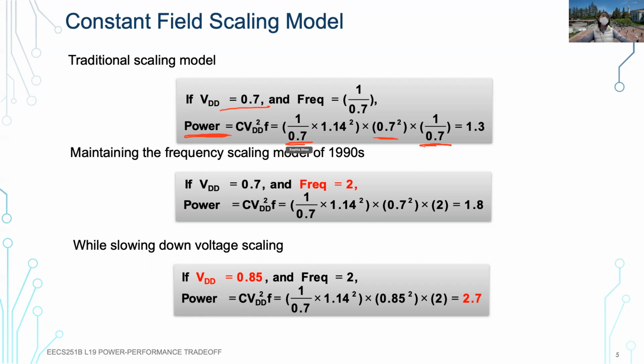Because our device is smaller, right? The dimensions get smaller, our capacitance is also getting smaller. We do have one factor that's actually getting bigger, right? This is more associated with area, right? So if we make our capacitance smaller, the die area, we still want to have bigger dies, right? So the die area has been increasing in the past, right? So we can afford more transistors here. We have a bigger die, so we do have a bigger die area. So then the power increased mostly due to the die area increase.